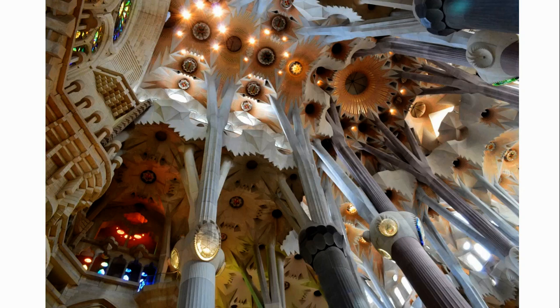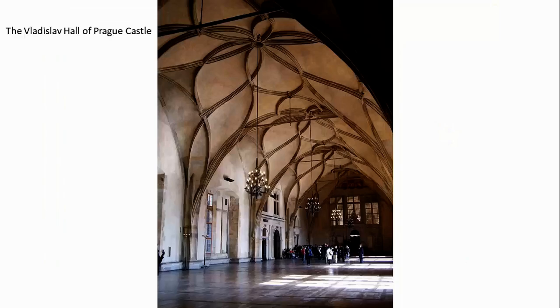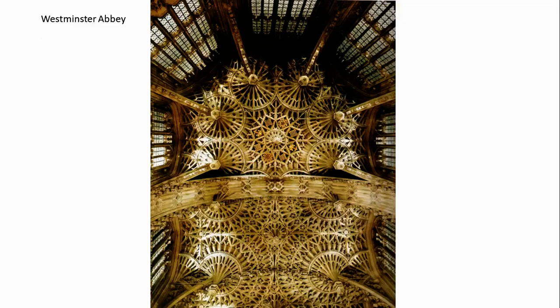So all of these arches are pure, these are working in pure compression, because we're working here with stone now, aren't we? Stone, as we've said, is a low tensile building material. There is no tensile strength in it. Therefore, everything's in pure compression in these buildings.